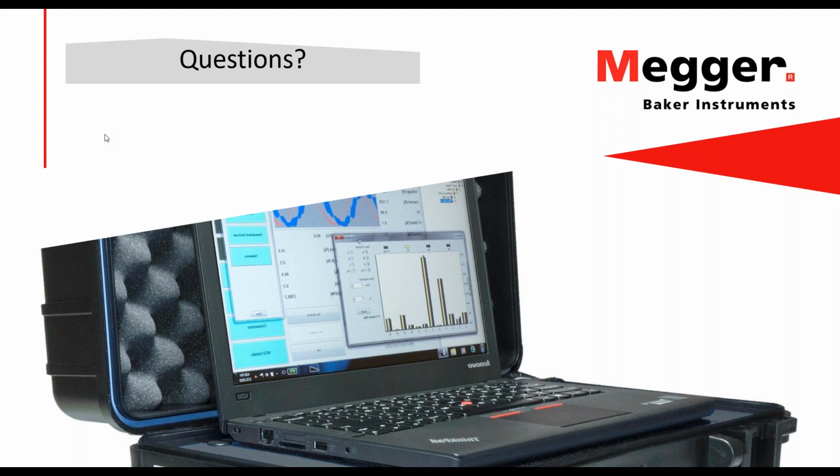So there we're using that, as I believe the caution level is at 7 and warning level at 9. Again, that follows, looking at IEEE standards. Current imbalance is set at 10% for a warning or caution. Then 120% of current would be a warning level on those. On voltage, we do 110% or 120% as far as caution and warning.